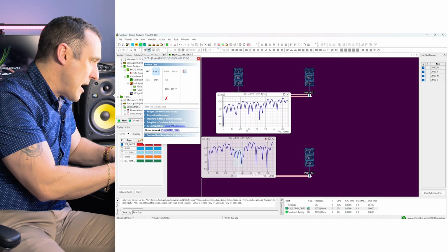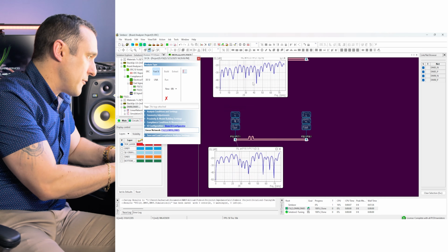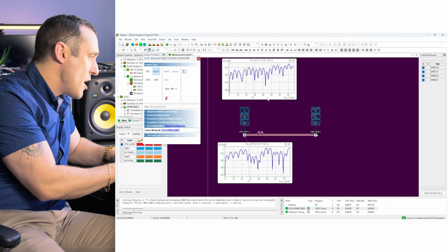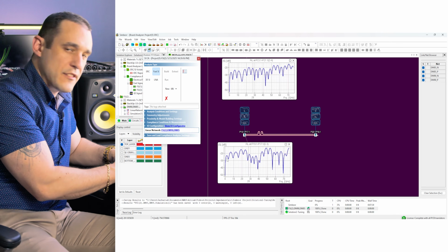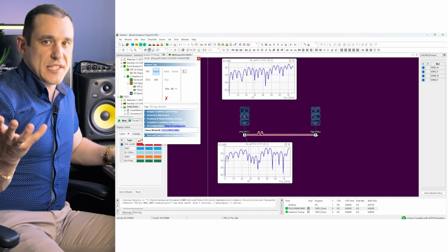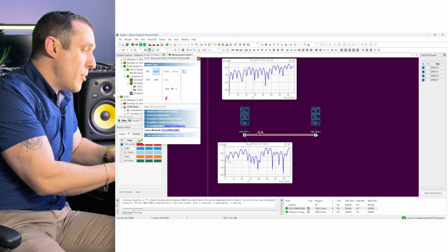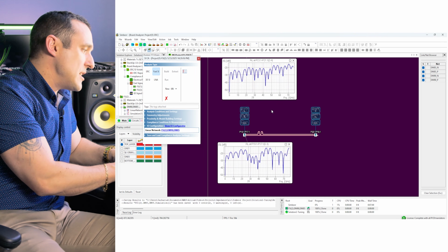I'm going to bring up this graph, I'm going to pin it, and you can see here we have very different S parameters now when we just add in those length tuning sections. So here you can see up to a couple of gigahertz or maybe about 5 gigahertz, we got pretty much the same return loss as we had in the case without the length tuning sections. But pretty quickly you can see that that loss rises above negative 20 dB.